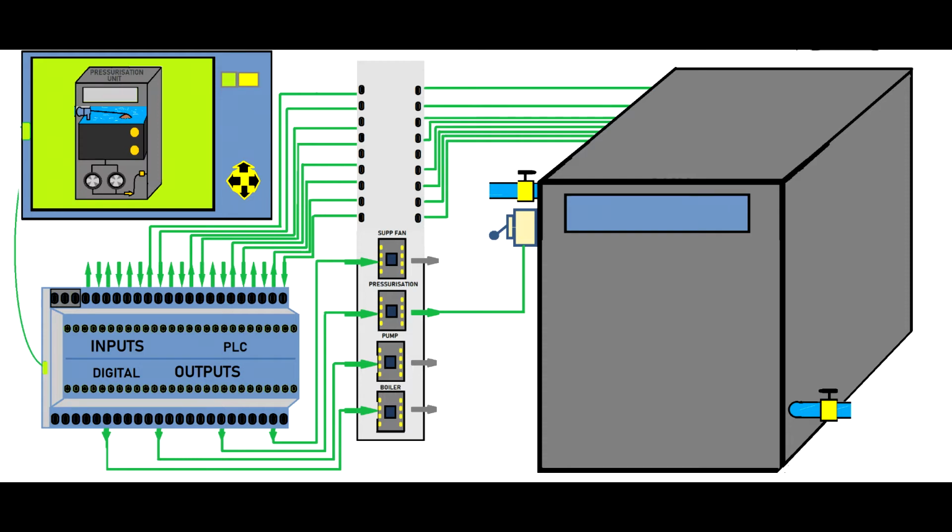After the welcome screen, the HMI will show you the item that you want to control, if the graphic is done well by the programmer. This is a good thing to think about: ask the programmer to do a good graphic design, so it will be easy for you to identify faults.